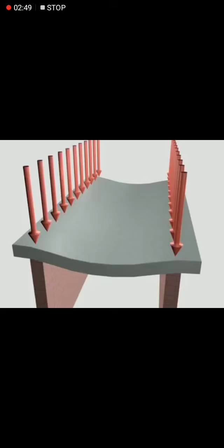Therefore the main reinforcement should not be provided as plain bar. It will bend at 45 degrees at a particular span. That is also called a crank. Only the main reinforcement will be cranked.